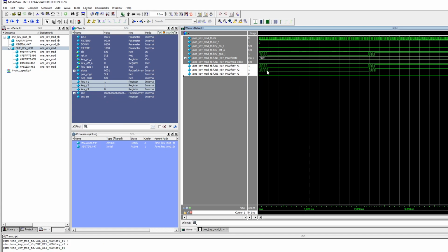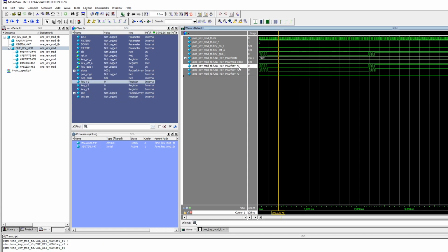You will see R1, R2, R3 are all shifted through the GPIO input, so the values should change according to the GPIO input. R1 and R2 are changed and shift 1 bit, but R3 didn't change. So the problem is R3.